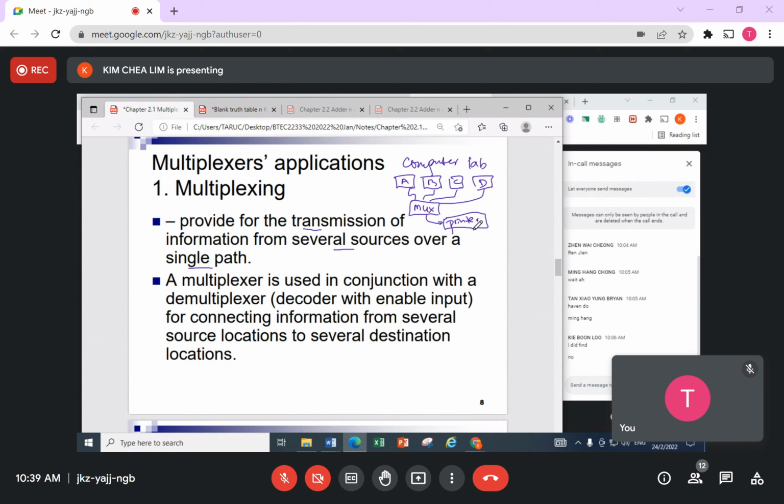So if you need to print, you send a print request to your multiplexer, maybe send a 1 here. If you are not sending anything for printing, the input coming in to the multiplexer is 0. So there is a selector here. The selector keeps on rotating, they keep on scanning. Remember something like a ring counter, they keep on rotating. Oh, now they saw a 1 here, coming from A. So what is the A condition? 1. 1 means that my printer is going to print.